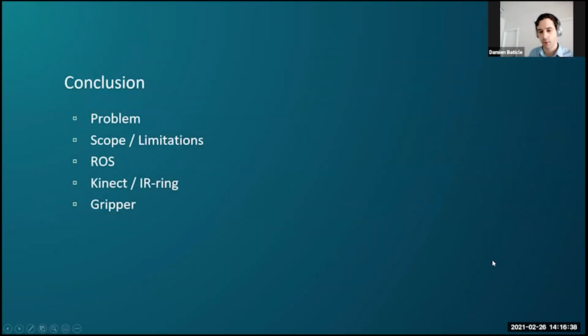In conclusion, our task that we were given is to move the work trays in between the work cells using a Robotino safely by avoiding static and dynamic obstacles. We chose ROS because it's adaptable, open source, and there is great documentation available. We're using a Kinect depth camera, infrared sensors that already exist, a bumper for emergency stops, and we showed off our initial gripper concept.